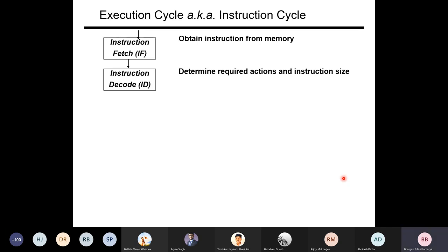the controller of your machine or the processor has been designed in such a way that in this phase of the execution cycle, it knows that I have brought an instruction from memory, right? So I need to interpret this instruction. So I need to enable the decoder circuit, which is built in hardware.